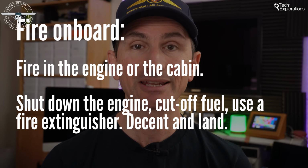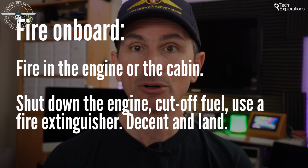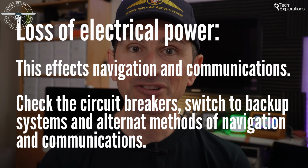Fire on board. Fire can occur in the engine or inside the cabin. The procedures for engine fire include shutting down the engine, cutting off its fuel supply, and using onboard fire extinguishers. Pilots typically use portable fire extinguishers for cabin fires while initiating an emergency descent. Loss of electrical power. Losing electrical power can compromise navigational and communication equipment. The basic procedure here is first to check circuit breakers and then switch to backup systems or alternate methods of navigation and communication.